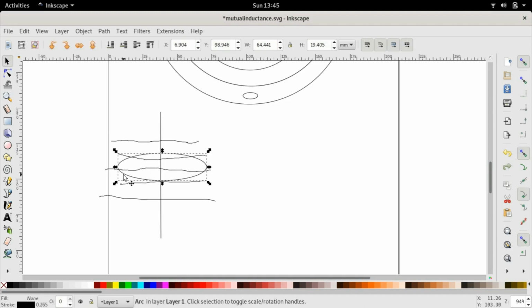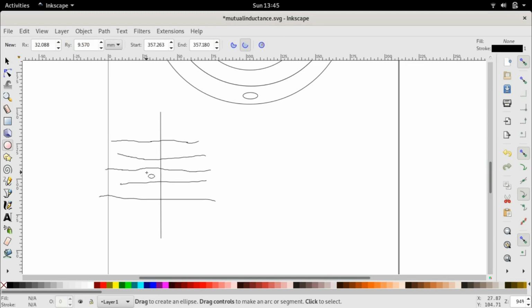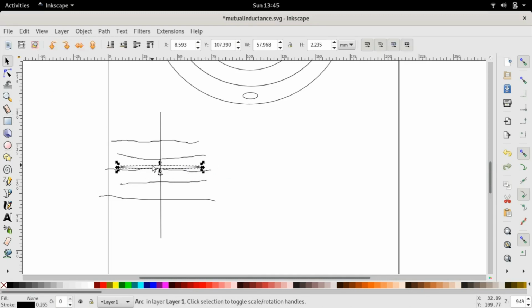Let me just draw a slightly slimmer rotor. Yeah, this is probably a little better indication of what I'm trying to do, right? So I have made this very slim to indicate that this is actually horizontal, right? So imagine there is a slight depth, and that's only because I'm trying to show it in 3D, but in reality this rotor coil is horizontal, and therefore it's quite obvious in this state that there is almost zero linkage of the stator flux with the rotor.